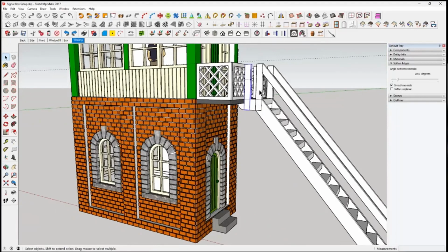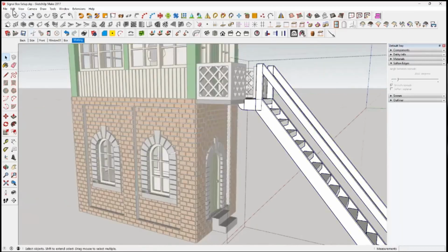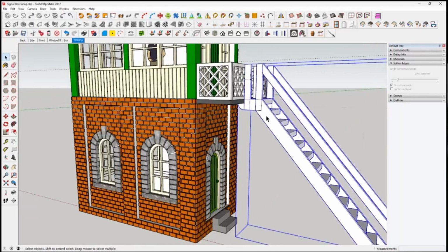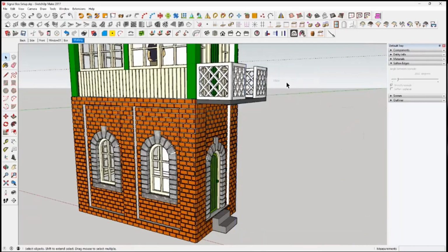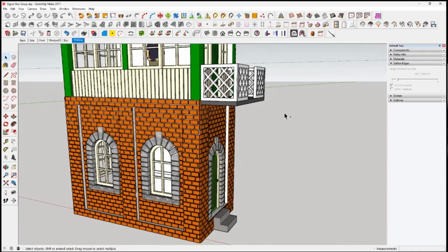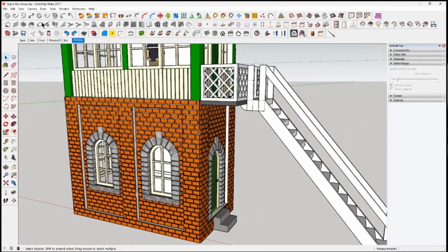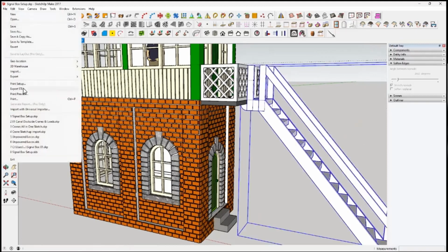So we click on that. It does need joining up there. We'll cut that one. Click on, double click, edit, paste in place. And we should be able to click on our stairs now. Right click, hide, and the stairs are gone. So we do Control Z. Click on File, Export, and we'll see what it's like in a slicer.